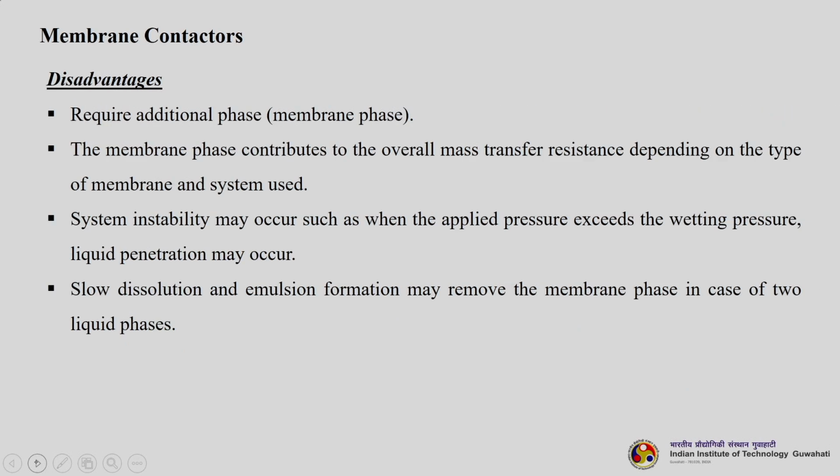However, it has certain disadvantages also. It requires an additional phase, which is here the membrane, and the membrane phase contributes to the overall mass transfer resistance, depending on the type of the membrane and the system used. System instability may occur, such as when the applied pressure exceeds the wetting pressure, liquid penetration may occur inside the pores. So, this is another problem. So, pressure has to be controlled very efficiently.